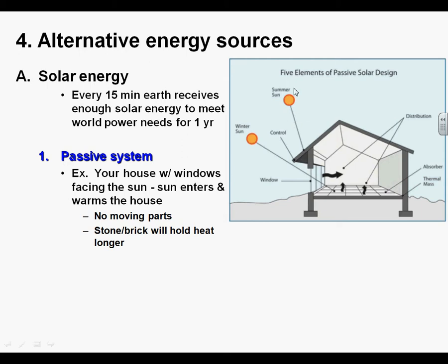In the summertime, the sun is higher in the sky because it's over the tropic, and it's not able to go inside the window if we have a large enough eave, which is an overhang of our roof. On my house, I have about a meter overhang of my roof, so the sun, when it comes down in the summertime, is blocked from this particular window right here.